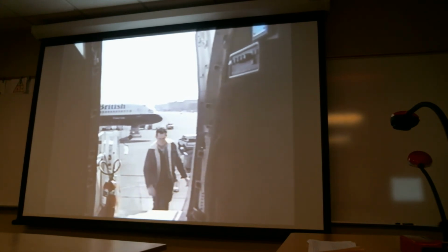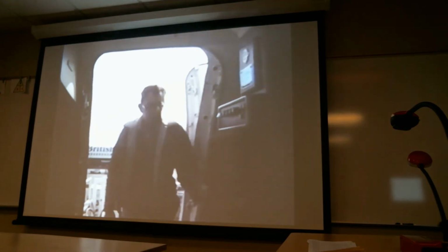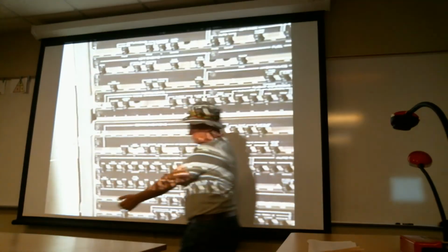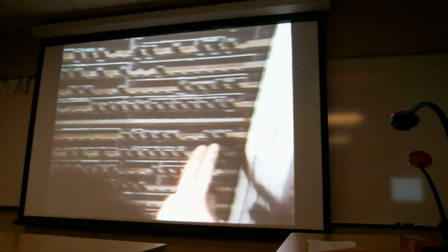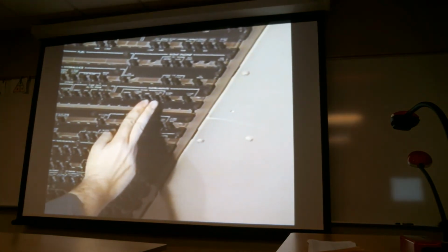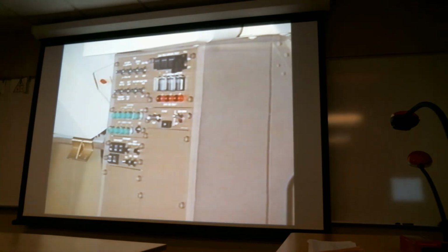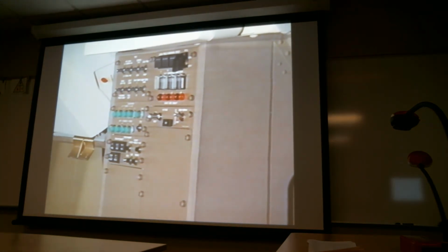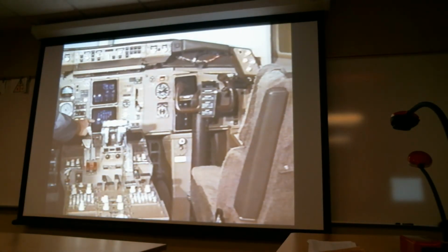Proceed to the flight deck and perform a hydraulic fluid quantity check on ICAS. On the flight deck, close the ICAS circuit breakers on the P11 panel. With power provided to ICAS, press the electric hydraulic switch on the P61 ICAS maintenance panel. Check the hydraulic fluid quantities on the lower ICAS display.